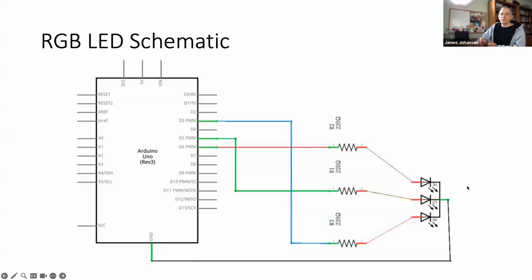And so a diode is really good at conducting in one direction and really bad at conducting in the other direction. So if you didn't have this, it would be like turning on your water faucet full volume. And actually it would likely cause problems with your diode here. So this is one of the reasons why we put in a resistor and this funny looking Greek symbol here that stands for ohms. And so this means it's 220 ohms.